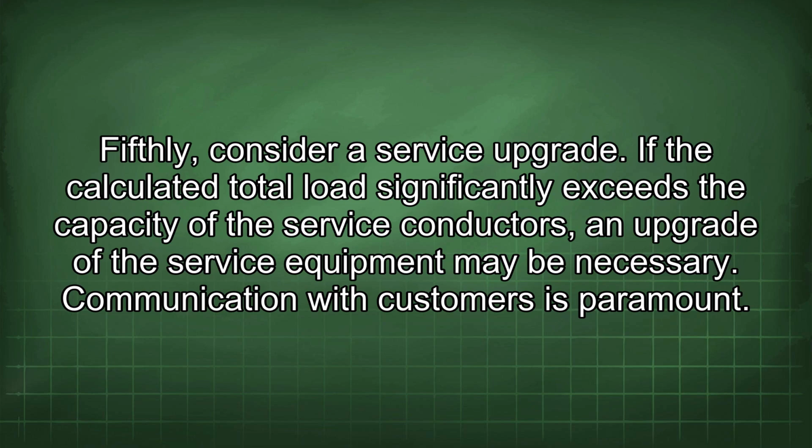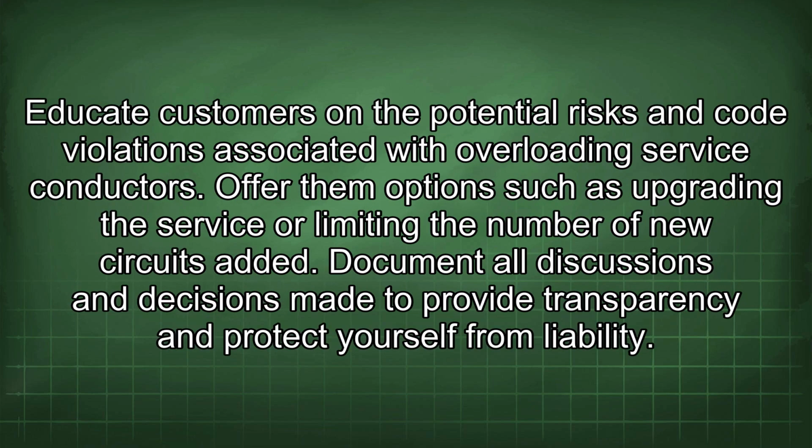Fifthly, consider a service upgrade. If the calculated total load significantly exceeds the capacity of the service conductors, an upgrade of the service equipment may be necessary. Communication with customers is paramount. Educate customers on the potential risks and code violations associated with overloading service conductors. Offer them options such as upgrading the service or limiting the number of new circuits added.